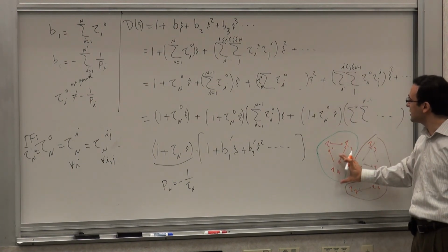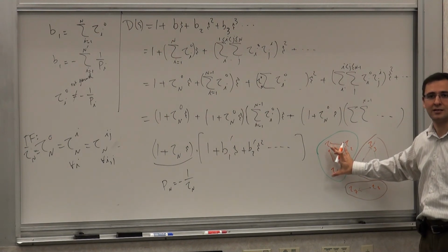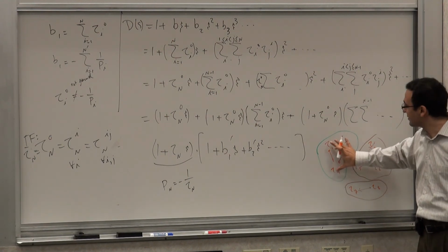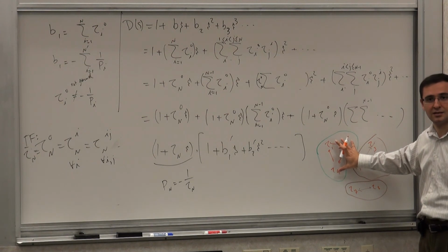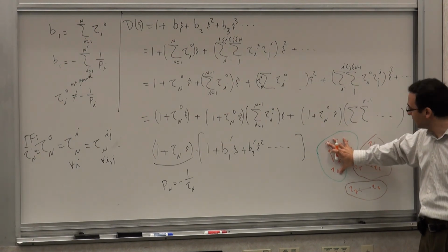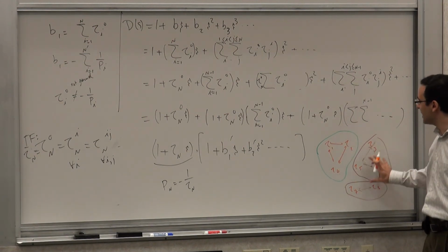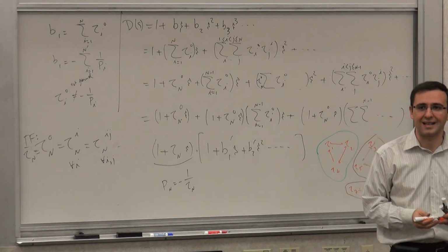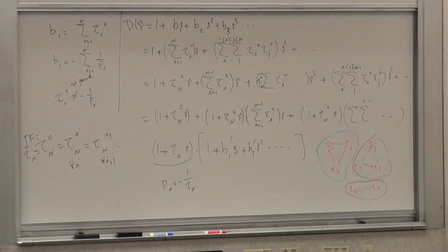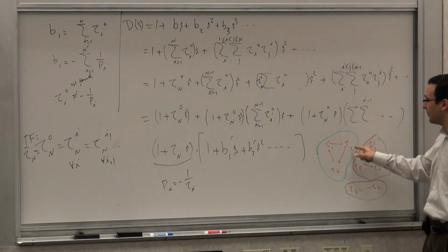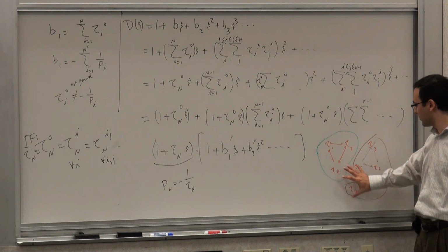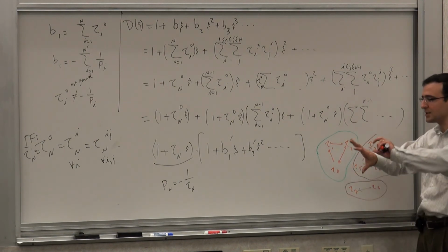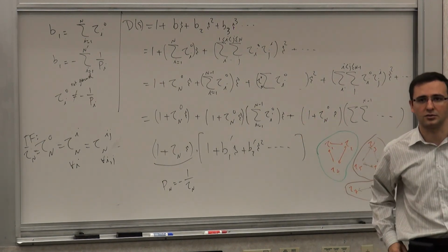And then you can basically treat this part of the circuit separately and apply the method of time and transfer constants to this one, calculate this transfer function, same here, and then the transfer function may be the product of them if they're cascaded, or some other combination. So here we're working with poles, but it also applies to the zeros, as long as they're uncoupled zeros too. This is primarily about the poles, but if the circuits are really isolated like that, then the zeros will be isolated.